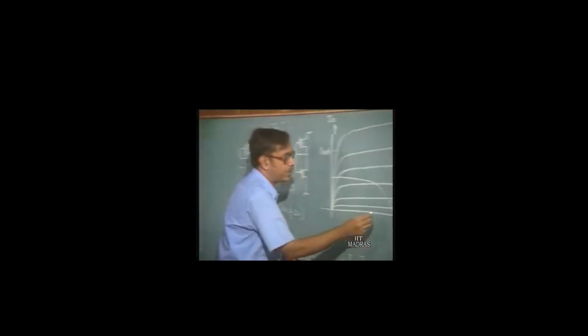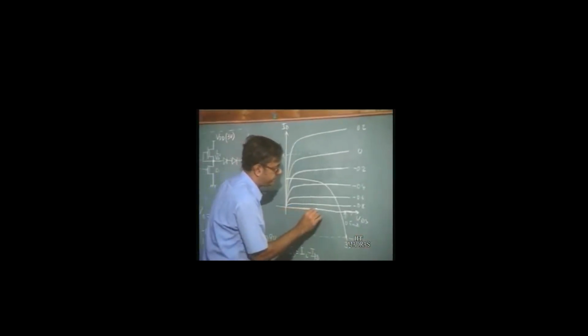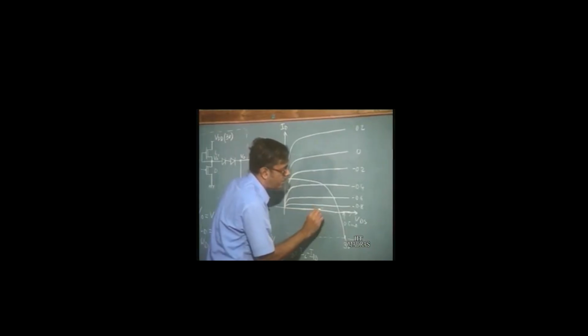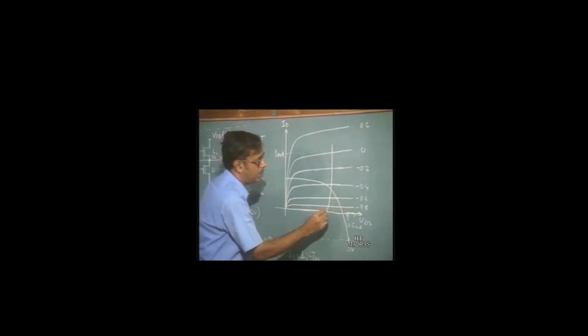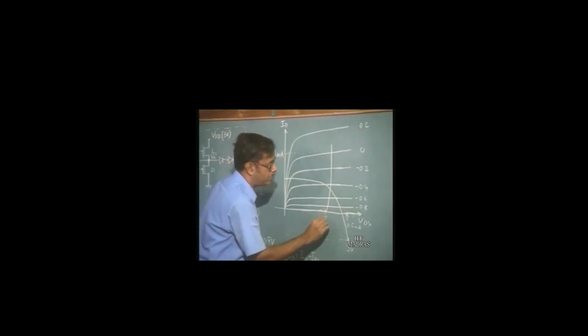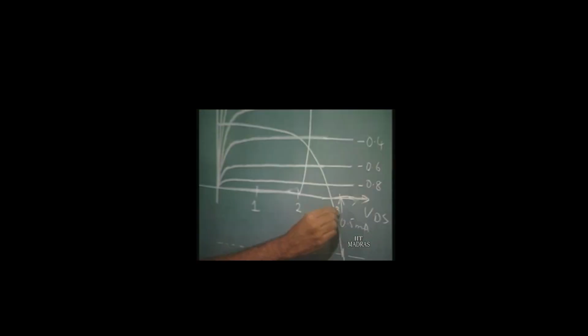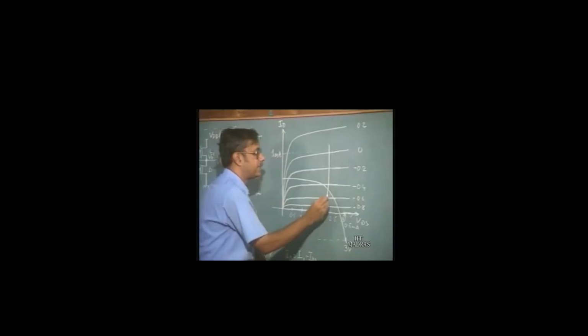So, we also draw the characteristics of the diode here. Okay. So, if this is 2 volts, this can be 1 volt, this is 3 volts. So, 1.5, 0.5 say, this is 2.5 and so on and so forth. So, this is the characteristics of the 3 diodes together.